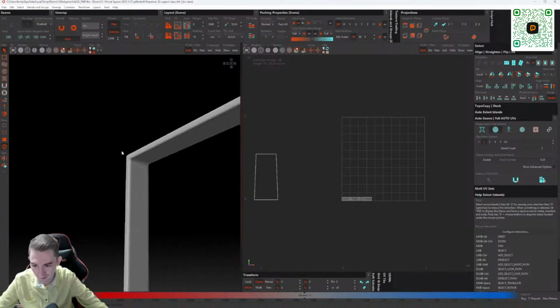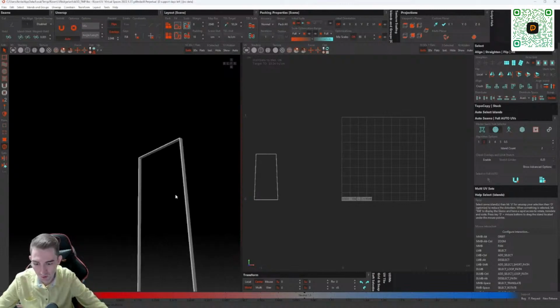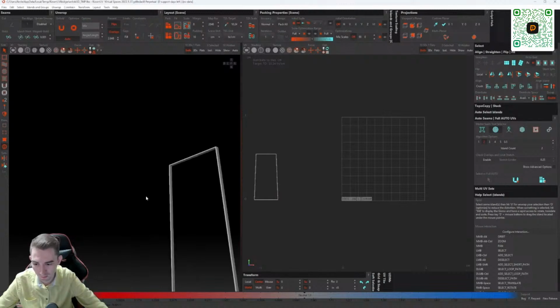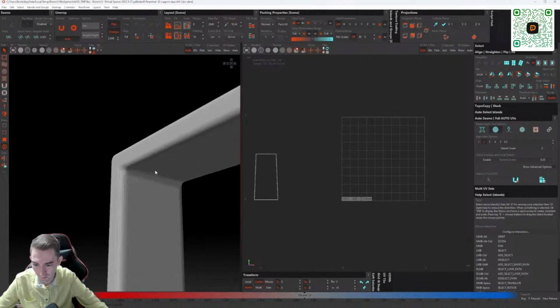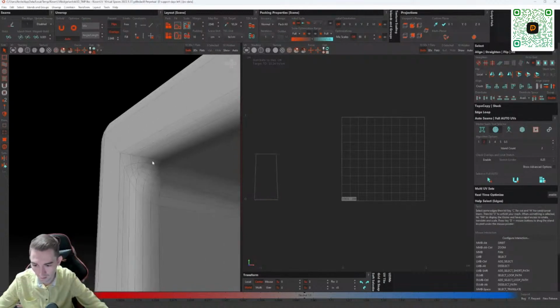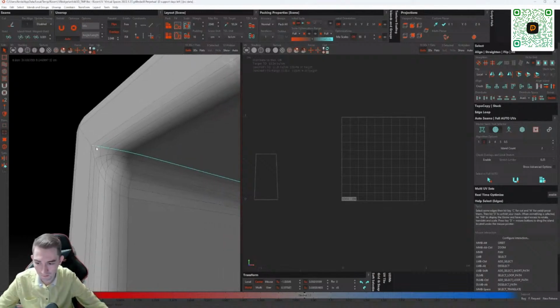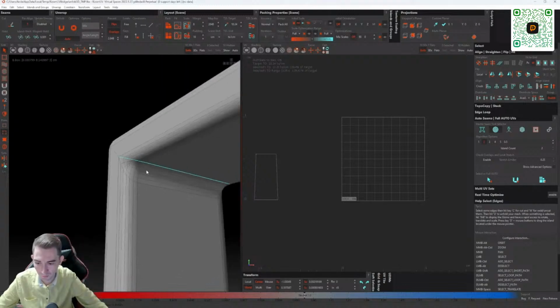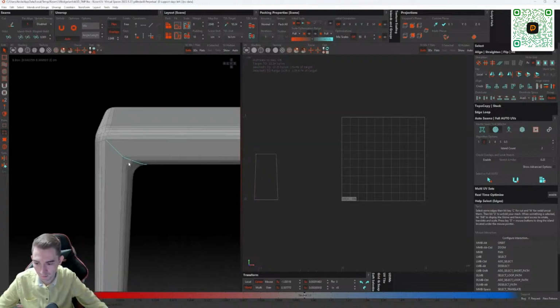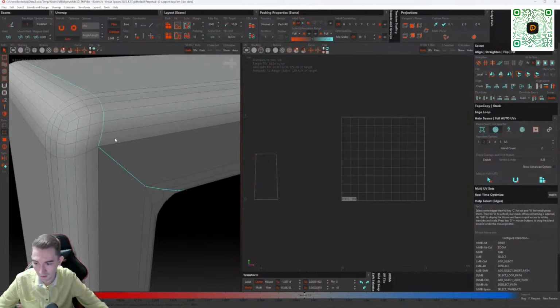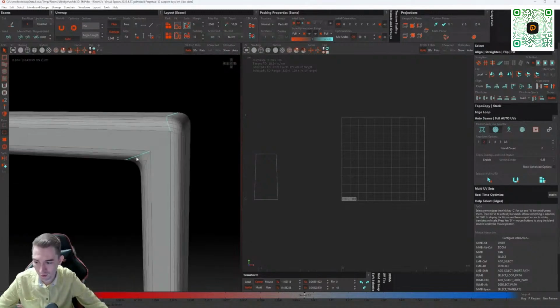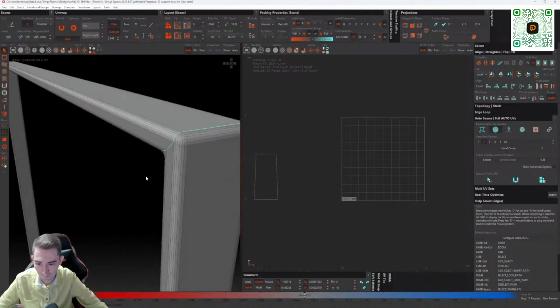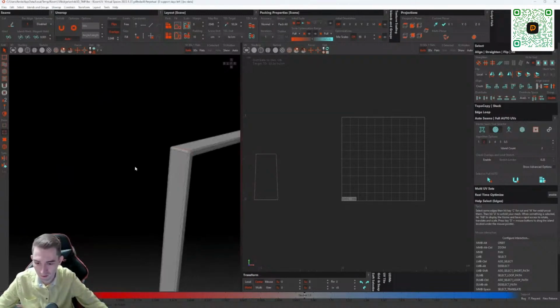Because I think it will not unwrap automatically normally. That is, in part, we switch to F2 mode. So, then here I press F, I double click, that is, we select a sequence of edges with a magnifying glass. And select them like this, continuing these edges here. Then I press the C key, that is, cut like a detail.